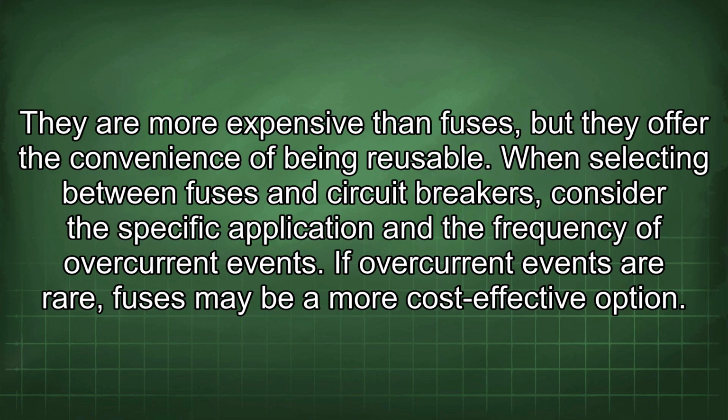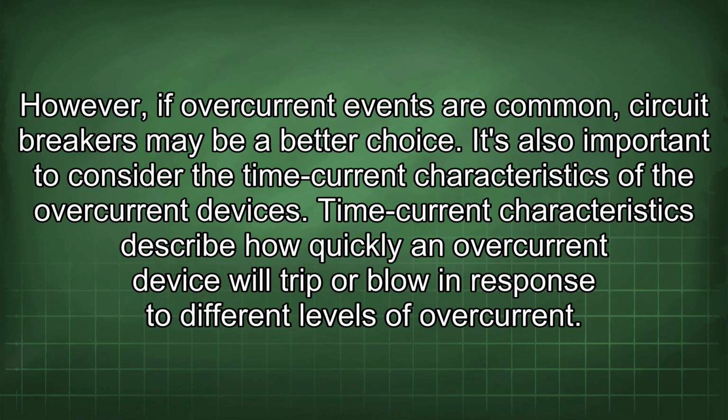When selecting between fuses and circuit breakers, consider the specific application and the frequency of overcurrent events. If overcurrent events are rare, fuses may be a more cost-effective option. However, if overcurrent events are common, circuit breakers may be a better choice.